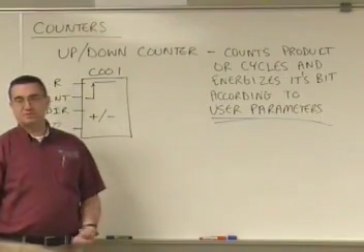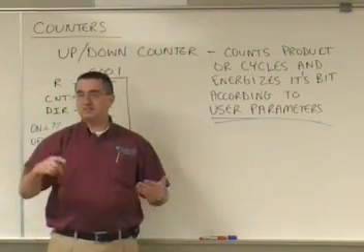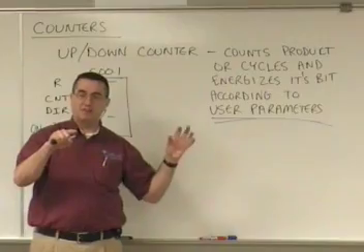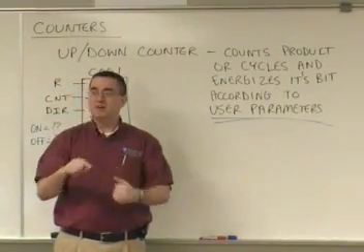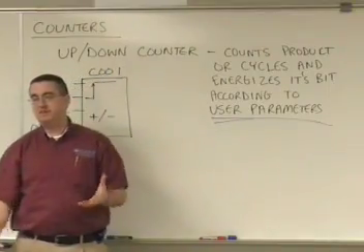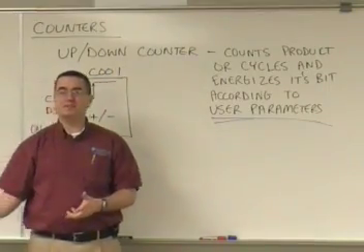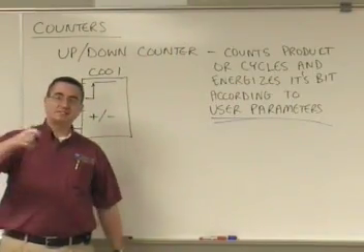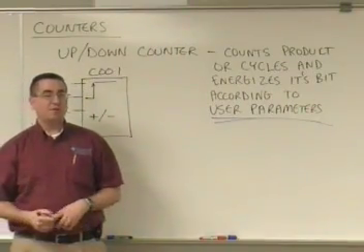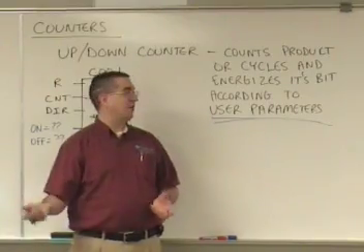So product counts could be, let's say I have a proximity sensor and I have metal cans coming past that proximity sensor on a conveyor belt. Every time I get that 12th can, I package a 12 pack. Every time I get that 24th can, I package a 24 pack. And maybe I can select between what I'm packaging. Or perhaps I'm just doing a total product count.